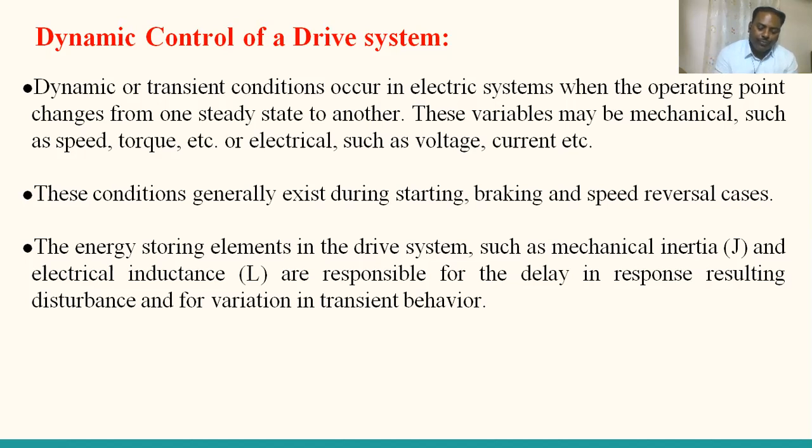So generally, starting, braking, and speed reversal are known as dynamic or transient conditions, and they arise because of the energy storage elements in the drive system, the mechanical inertia J and the electrical inductance L.